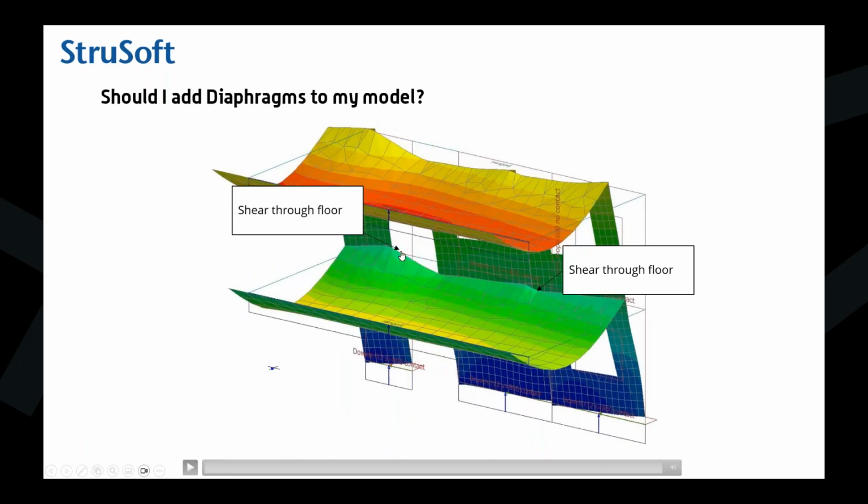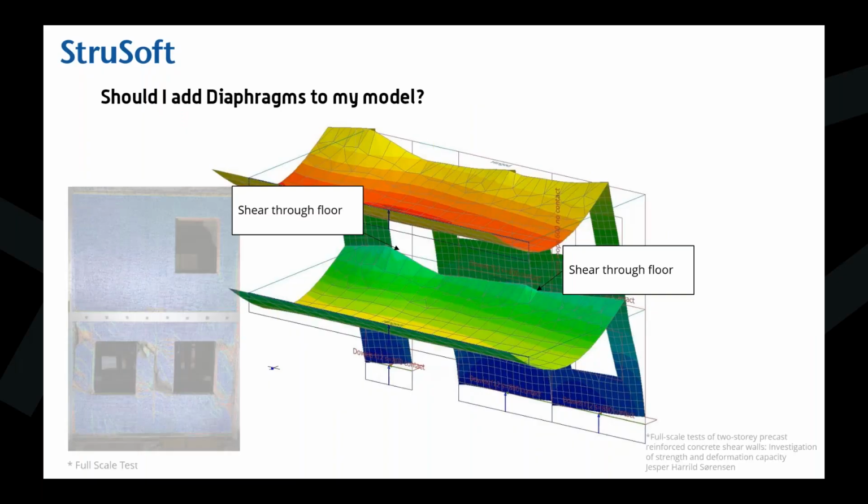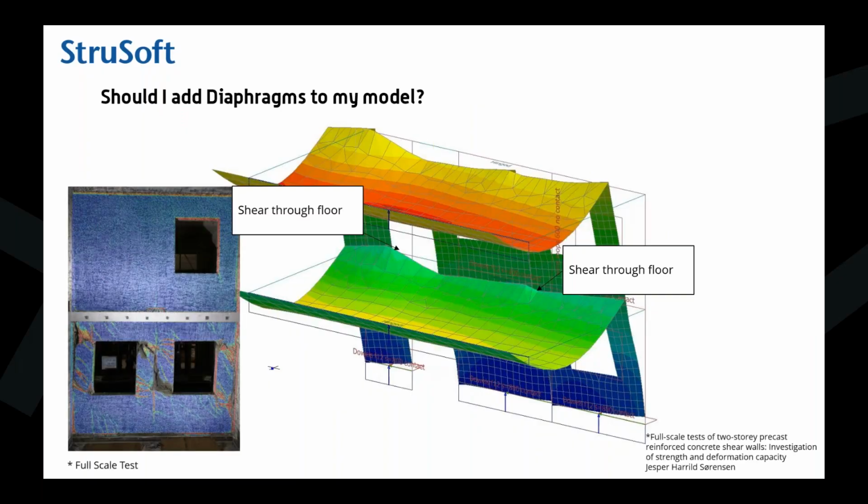And this is really difficult to isolate in finite element models, how much of this shear is now transmitting through the floor, and it's very hard to quantify and take out of the model. So that is the downside if you want to add floor plates. And also you have to now design this floor plate for secondary bending because this will stabilize your building now. So it might make a lot of sense to remove those floors.